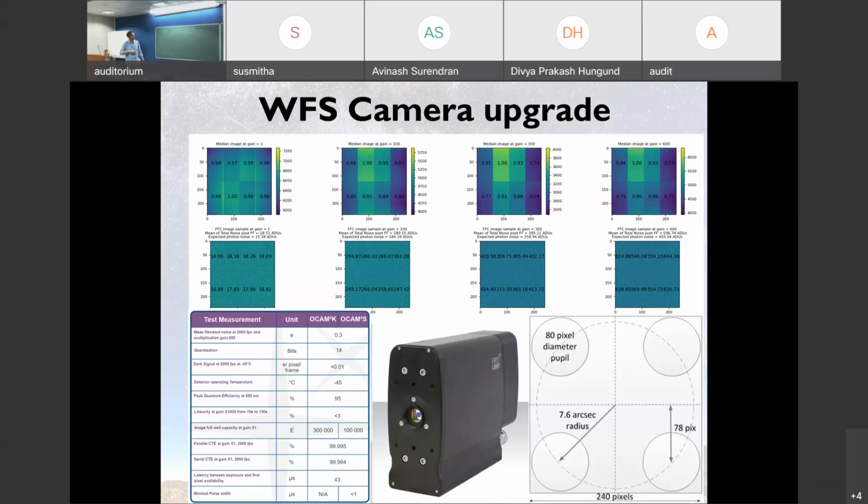Even in the characterization in the lab, it looks like a checkerboard pattern, as you can see, where it has multiple channels. It has 8 channels in total for the fast wavefront sensor readout. And the illumination between the channels can be very, very different, sometimes of the order of 3 or 4 times, where you need very good flat fielding calibration, and maybe it may change over time.